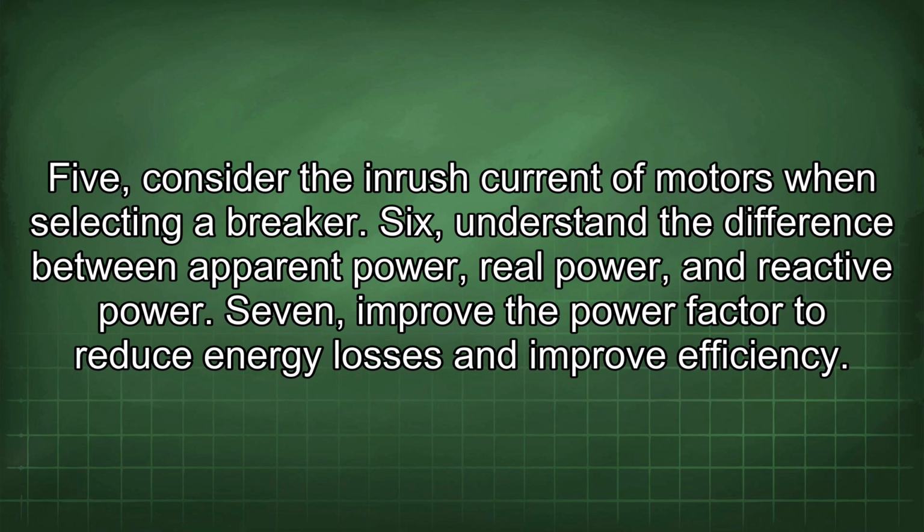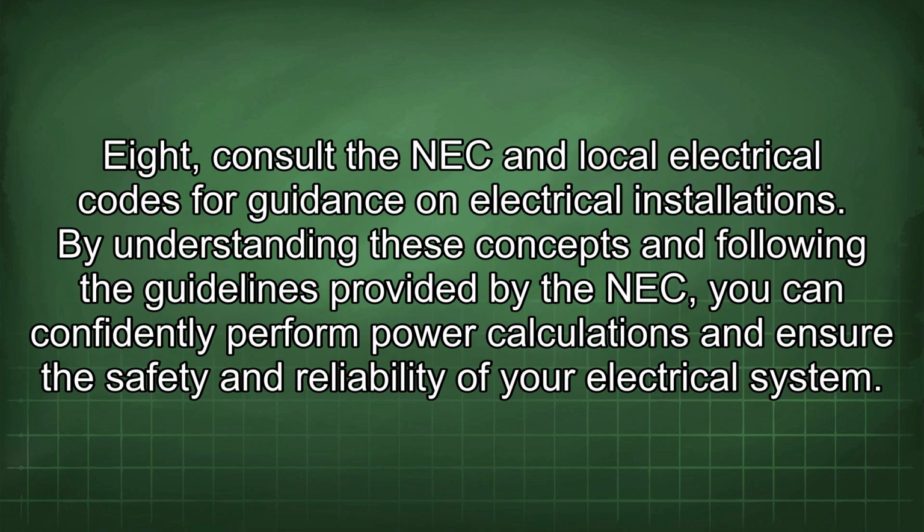5. Consider the inrush current of motors when selecting a breaker. 6. Understand the difference between apparent power, real power, and reactive power. 7. Improve the power factor to reduce energy losses and improve efficiency. 8. Consult the NEC and local electrical codes for guidance on electrical installations. By understanding these concepts and following the guidelines provided by the NEC, you can confidently perform power calculations and ensure the safety and reliability of your electrical system.